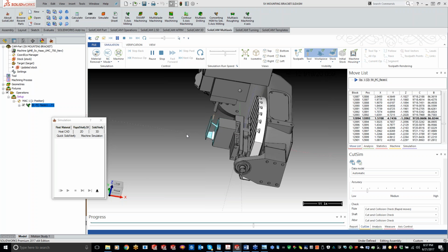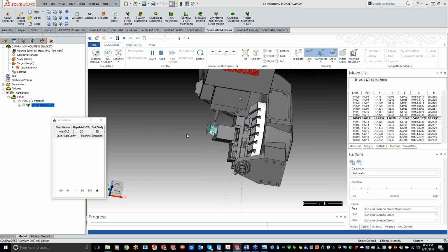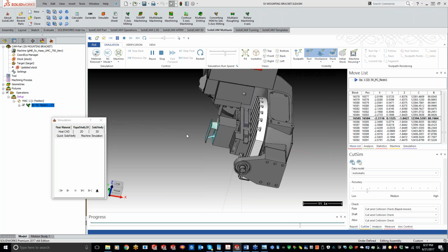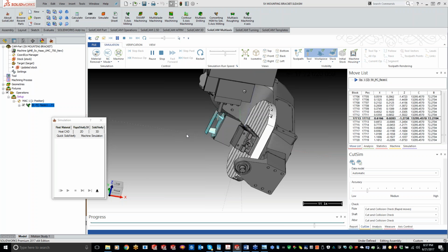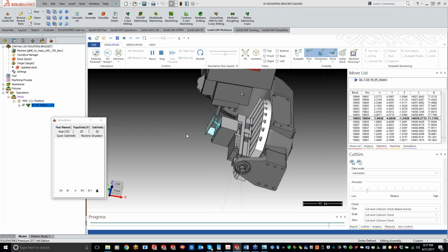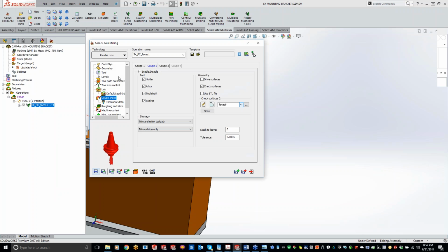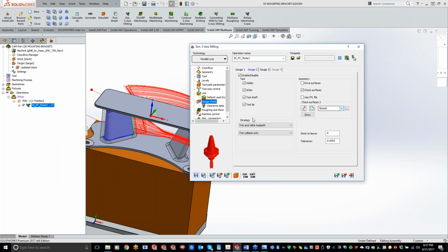Don't go through the entire operation doing everything you think would be correct. Just grab your surfaces, and if you want to do a spiral or one way or however you want to do it, do a save and calculate. Then see where your toolpath is at. Then start getting a little bit deeper in. Take it in stages. Don't try to do it all at once. The biggest thing is, you start changing stuff in here and it's just not working. So like I said, take it in baby steps.